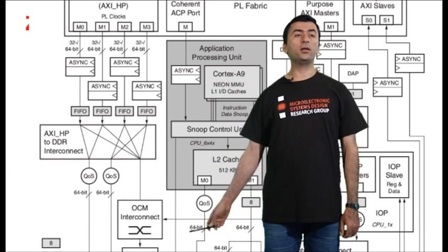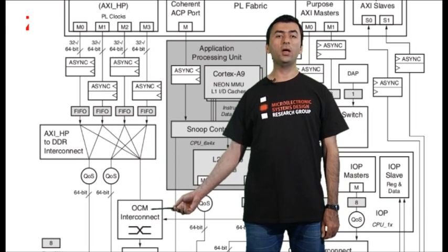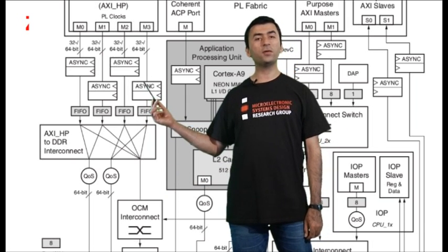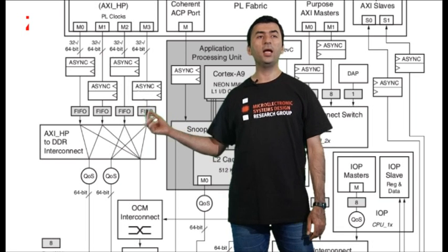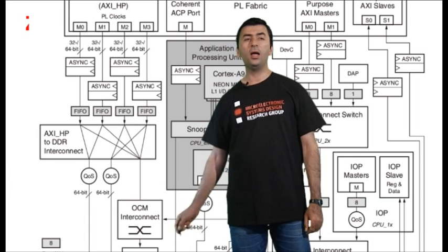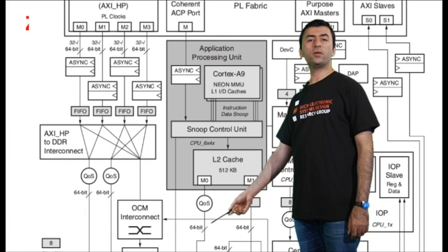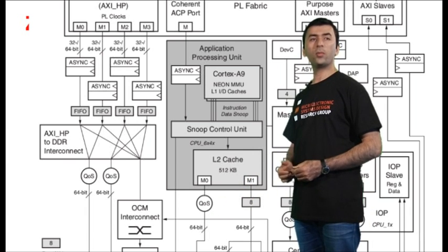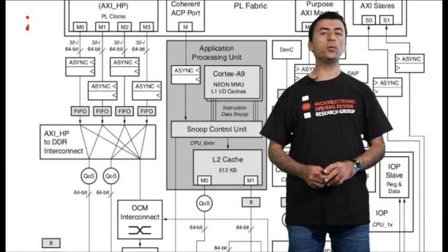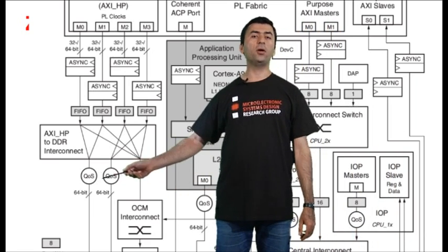And the interconnect is driven first by this AXI HP interconnect, meaning that every module that you have connected to each of the HP0 to HP3 ports can, through this OCM interconnect, access the OCM. And furthermore, as we will see, the rest of the components inside the system also have the possibility of accessing the OCM. So let's scroll down the map a little bit more and see what will happen to these 2 signals here.